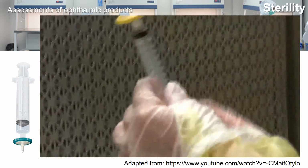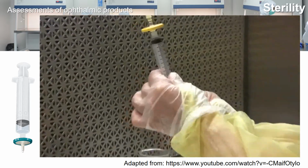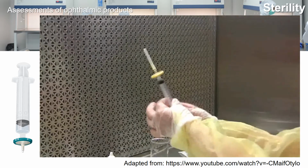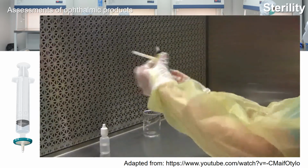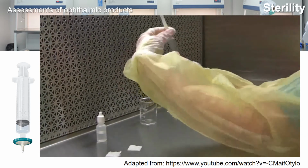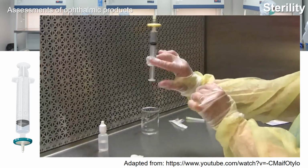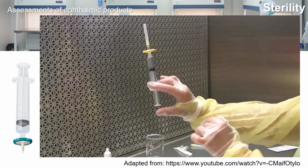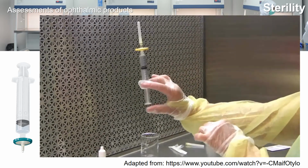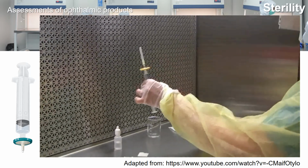You can try to pull down on the plunger, and you should feel resistance. You can't pull air into the filter. Also, you can draw air into the syringe, and you will not be able to push that air through. You'll feel resistance. The air will not pass through the filter. So that means your filter has been intact the whole time.